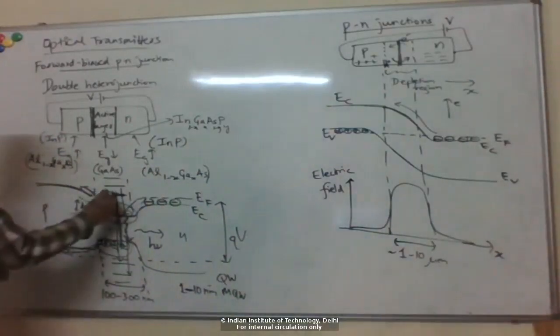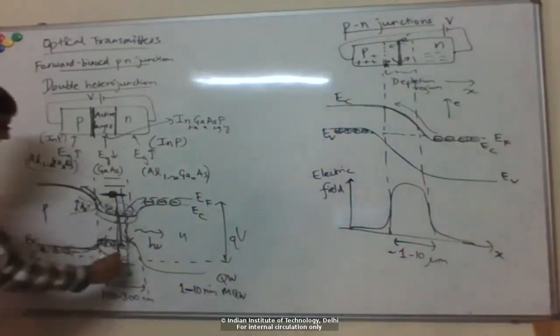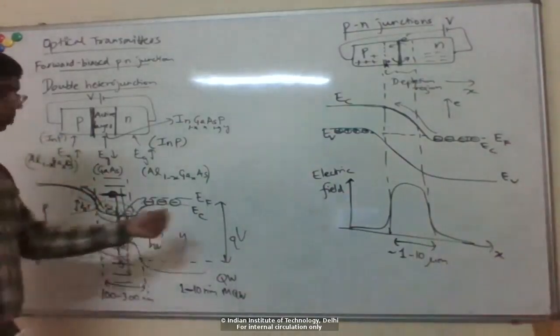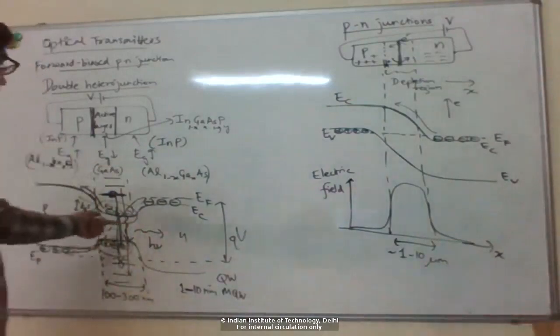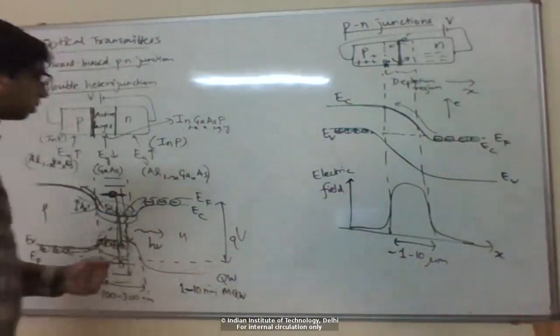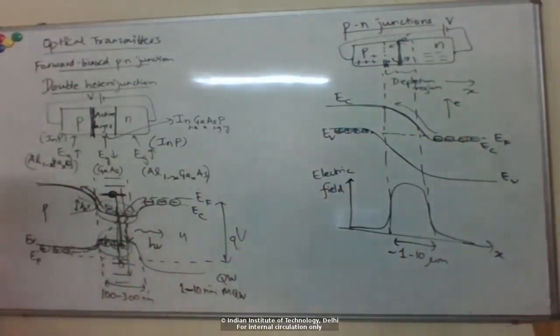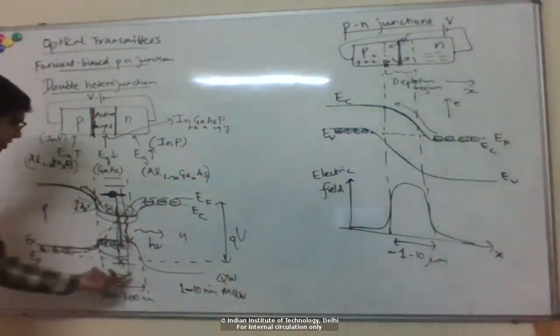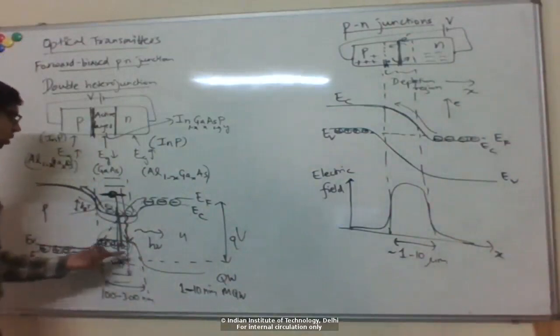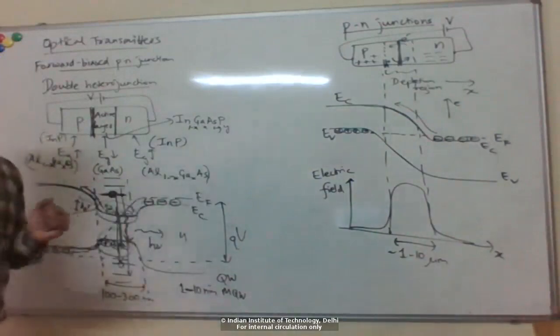But now, if you have discrete energy levels, then the energy of these recombining carriers is very well defined. So the energy level difference is very well defined, and the wavelength or the frequency of the light emitted is also well defined. That's one way of making single frequency lasers. But we'll see that even with these wider, easier to make, cheaper active layers, we can do something externally.